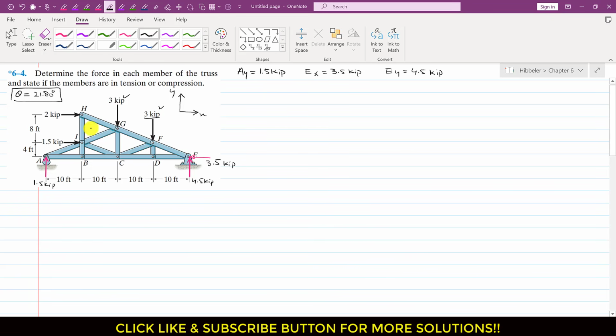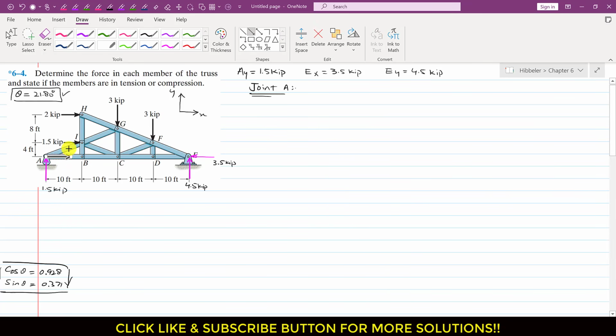Now we will start from this joint A, since at joint A we have one known force and two unknown forces. We usually start the solution with that particular joint where we have at least two unknown forces and one known force. So now we will consider joint A for equilibrium. Let's assume that at joint A, member AB is applying the force in this direction, and similarly, member AI is applying the force in this direction.